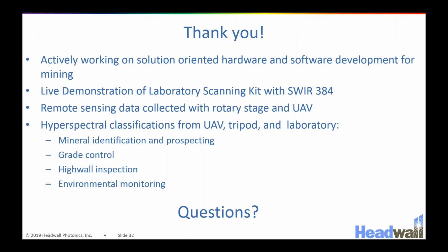The question was how we get SWIR wavelengths, because the NEON sensor needs to be cooled. The answer is our sensor also needs to be cooled, and we use a Stirling engine to cool our sensor, our focal plane, to 150 Kelvin.